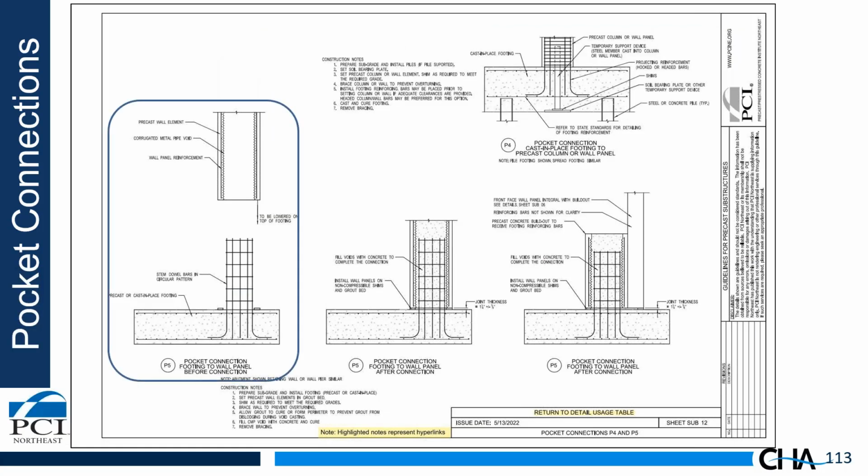This next detail, I'll give credit where credit is due. Maine DOT, that Kittery Bridge, they use this detail too, where they actually took a cast-in-place footing and had reinforcing bar clusters sticking out of the footing, and then they set the wall element on top of the bars using the corrugated metal pipe voids to connect the two. So here's a photo showing that.